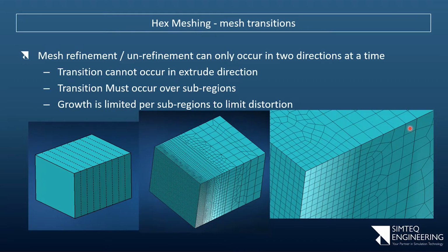By doing that, and again on purpose, I went from that number of elements on that edge to that number of elements on the vertical edge as well. So that last row of elements is actually the nicely shaped elements. It's the perfect or close to perfect elements. So then I swap it again. In this case, I went for coarser mesh again in this direction, but I could have done it on top. It's just which direction you're doing it.